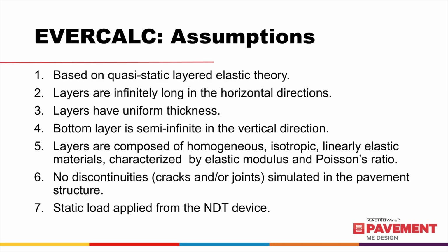There are some specific assumptions based on which EverCalc has been built. The assumptions are based on quasi-static, layered elastic theory. Layers are indefinitely long in the horizontal directions. In other words, anisotropic conditions and cracks or defects cannot be directly simulated. Anisotropic conditions means the properties in the vertical direction can be different from the horizontal direction.